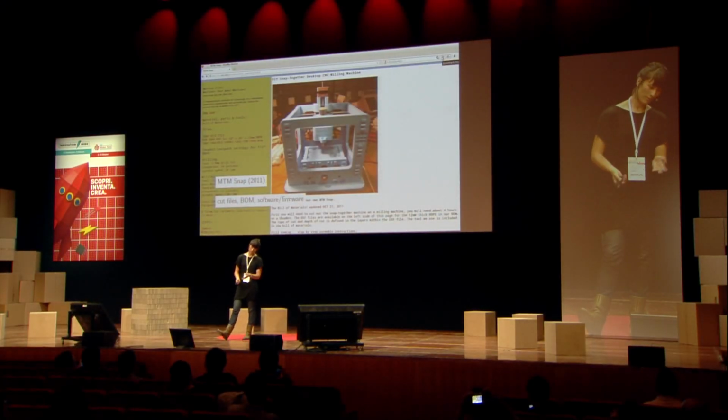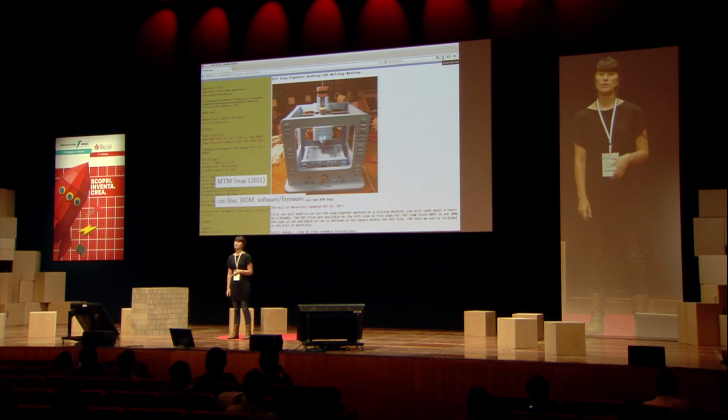So the MTM Snap is a series of design experiments at the MIT Center for Bits and Atoms that started with people coming in and making their own Fab ISP so they can program microcontrollers, but they can't necessarily make their own circuit boards at home. And in the Fab Lab inventory, we made the broad sweeping decision to include all 1206 surface mount parts as an easy way for people to prototype different kinds of hardware. And so can you mill, and we use a Roland Modela to mill circuit boards, to make surface mount and some through-hole component circuit boards for people to prototype with.